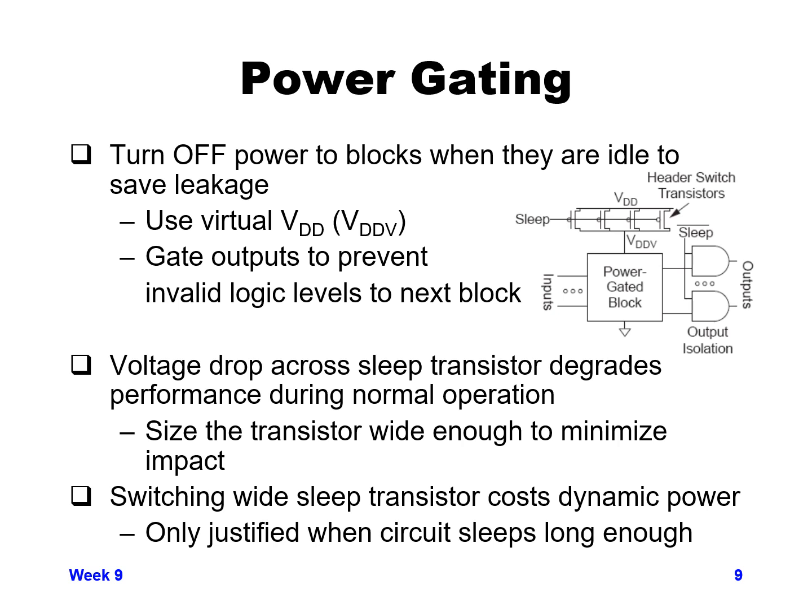In effect, you wouldn't be able to do it from one cycle to the next anyway, because it would take a while for your voltage to stabilize on the other side of the sleep transistors. But you probably wouldn't even want to do it on a 20 cycle or 50 cycle basis. You'd probably only want to do it when you know that you're going to be sleeping for long enough, maybe 100, maybe a couple hundred cycles. If you know you're going to be sleeping long enough, you can turn the logic off for a longer period of time.